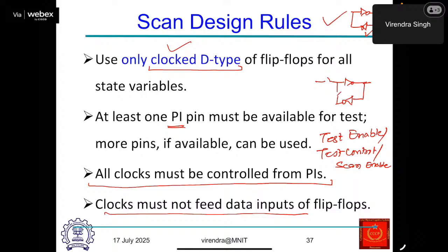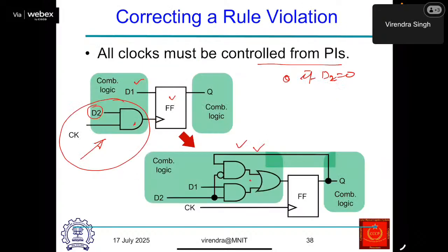So this scan design provides additional support for debugging. It's not only used for testing, but also for debugging. And JTAG is one such interface in which we can use this scan chain to scan out all the contents of the flip flops, and then you can debug in a much easier way.